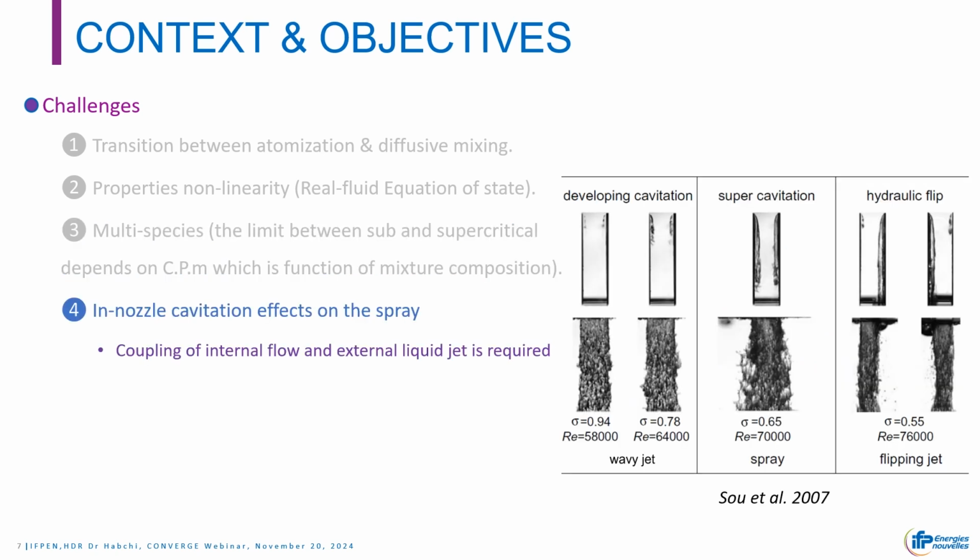Another challenge is the simulation of the in-nozzle cavitation effect on the spray. As shown in the experimental work of Su, there is a significant coupling of the internal flow and the external liquid jet atomization. Therefore, we need to be able to compute such coupling of the in-nozzle flow and cavitation.